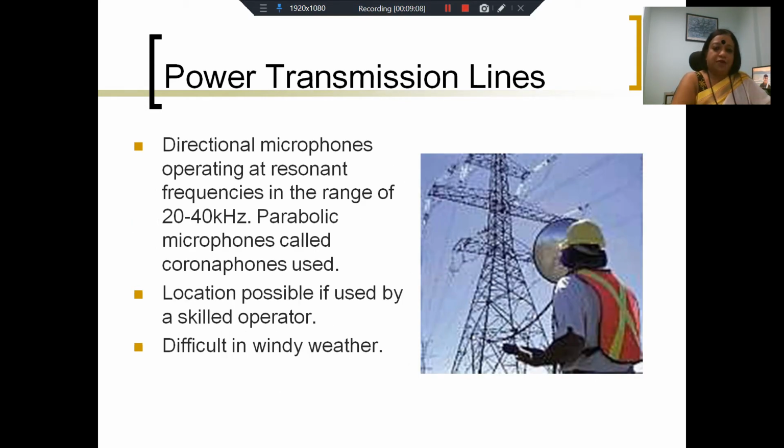Actually, acoustic emission techniques came to be used quite casually when we were talking about corona. If you remember, corona is nothing but partial discharge happening in open air. Corona routinely happens in power transmission lines. And in fact, even today, you can hear corona happening. So the best detection technique for corona is often your ears. You can hear the sound that comes from corona, and a trained ear can very quickly pick up the characteristic sound that happens from corona.